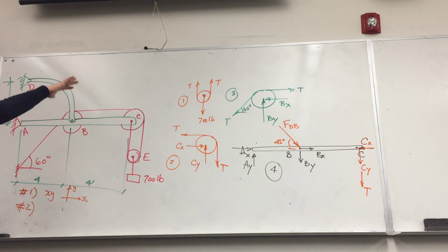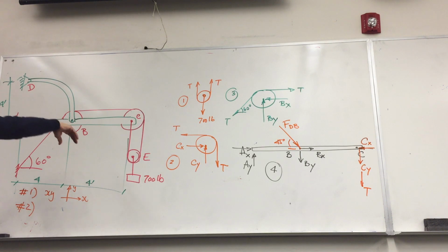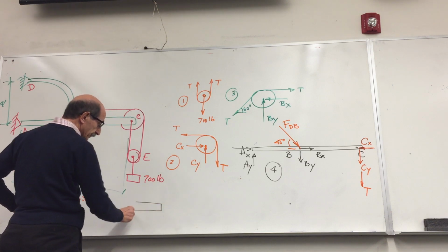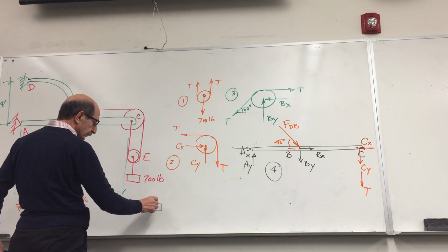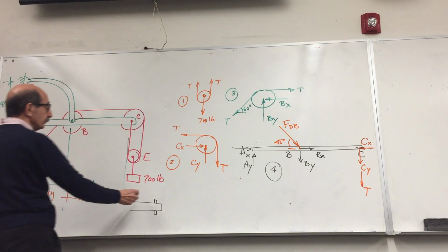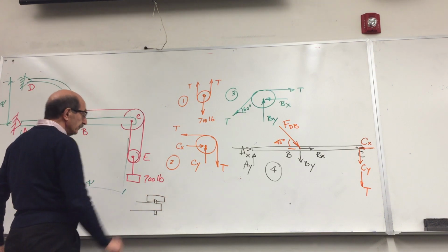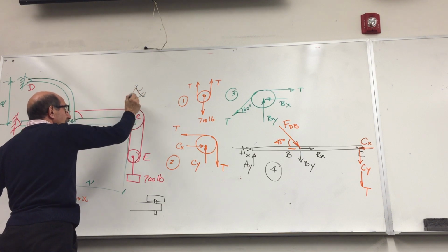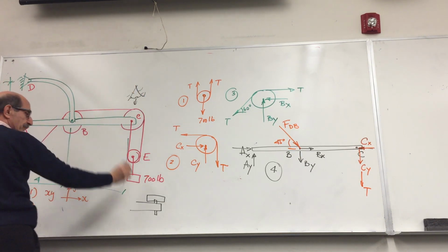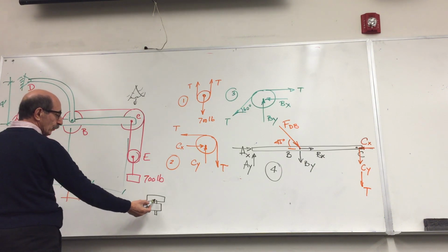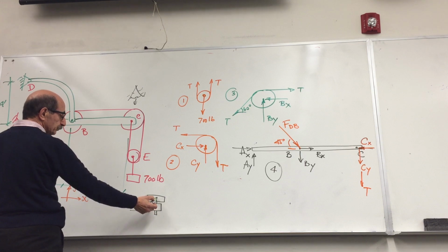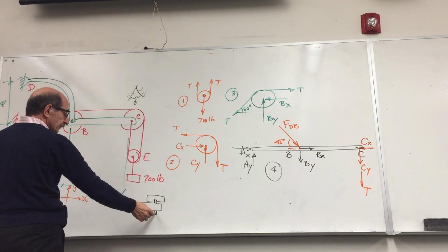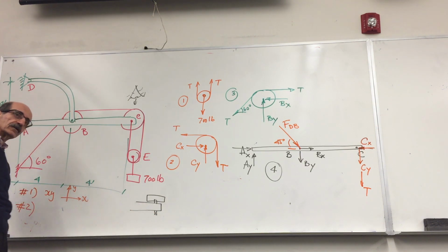See, this is, I mean, of course, we had given the top view also. You look at it like this, I mean, this is what you have. At C, this is what you have. If you look at the top view, right? This is what you have. You have a pin, right? This pin is holding this pulley. That's the pulley. This is C from the top view, looking like this. So if you're looking at it that way, there's a pulley that this pin is supporting. So there's a force that this pin exerts on that pulley and vice versa. That's the force I have given here. But then this cable is attached here. So it's going like this, right? So that's where those three forces are coming from.